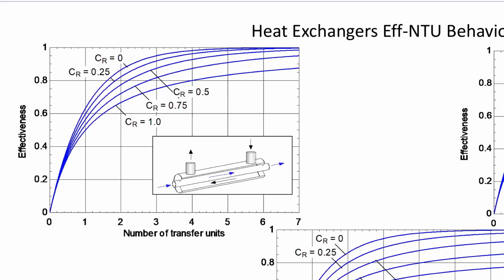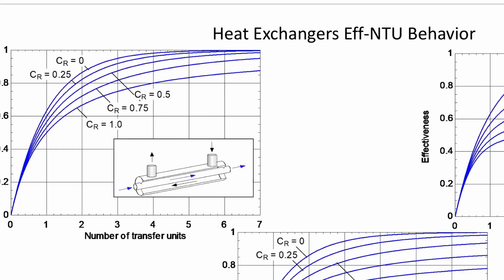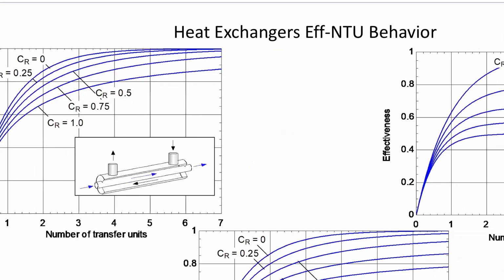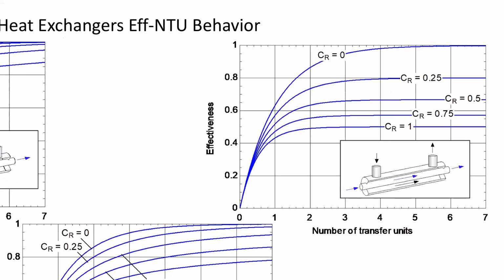So this is one plot in terms of counterflow, but you do see also that you can get effectiveness much higher than say 0.5. You can get pretty effective heat exchangers as opposed to a parallel flow heat exchanger, where if you have a perfectly balanced parallel flow heat exchanger, what are you doing, right? We could plot it like this. You have your temperature coming in.